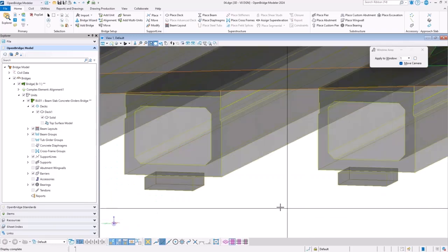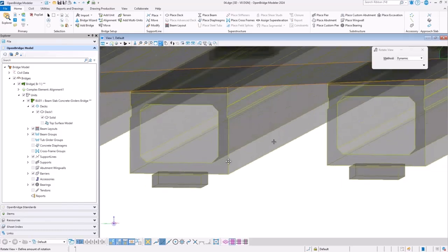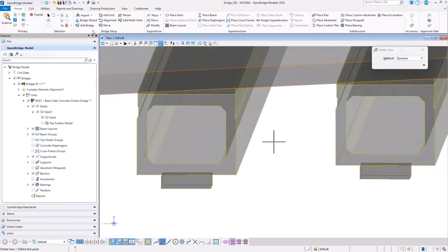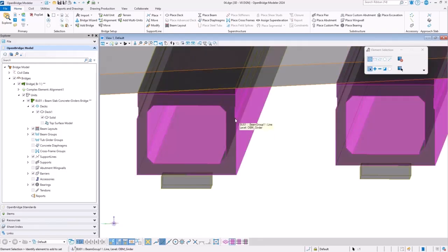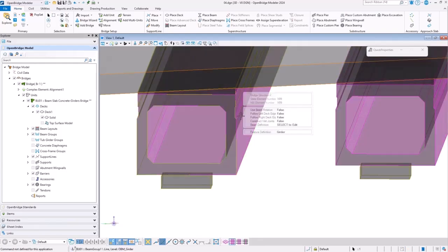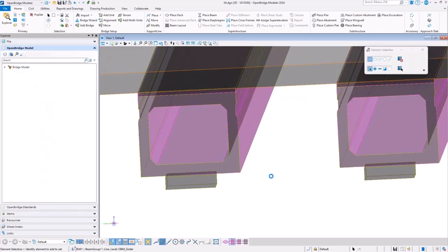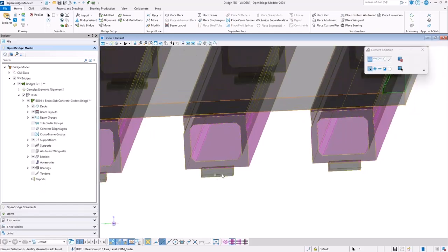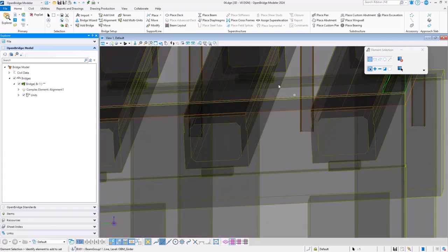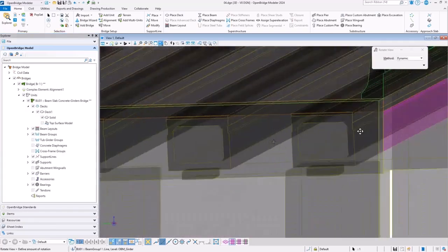Right here, for example, right? You see I have these box beams with no rotation. That's why you have the haunch here as a wedge. So now I'm going to edit these beams and apply the beam rotation option. And as it's true, it's going to rotate the beam, and then it will rotate the bearings accordingly. And then, of course, you will get the right geometry reports based on that rotation. So before, there was no way to do it other than manual modification.